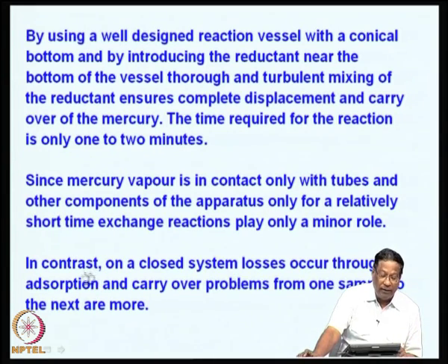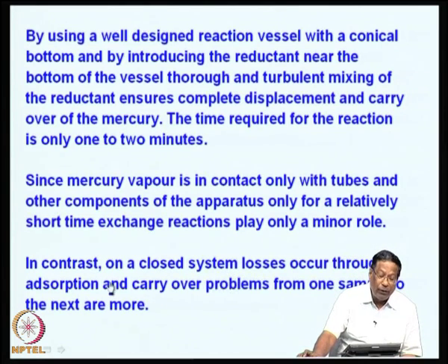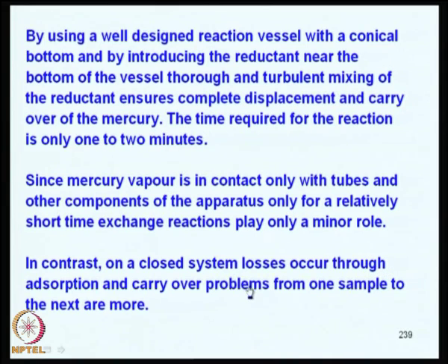In contrast, in a closed system, losses do occur through adsorption and carryover problems. Carryover problems sometimes give you an enhanced signal, because you are analyzing before the previous signal is completely dissipated, because part of it would have been adsorbed. So from one sample to the next one, whenever you are analyzing, you have to make sure that memory effect does not